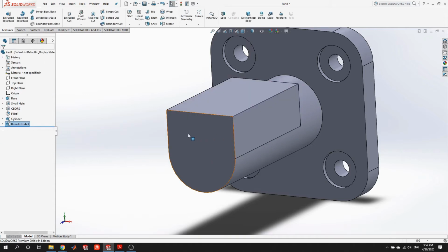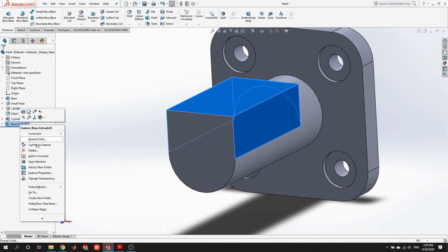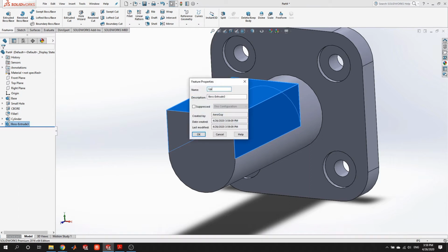Now I've chosen not to cut any holes into the cylinder just yet because I want this material to be absorbed. It will help make these features much easier. After that point, then we'll simply cut the circles in and we won't have to provide any extra relief cuts from the material intersecting. Perfect. All right, and we'll call this upper rectangle.